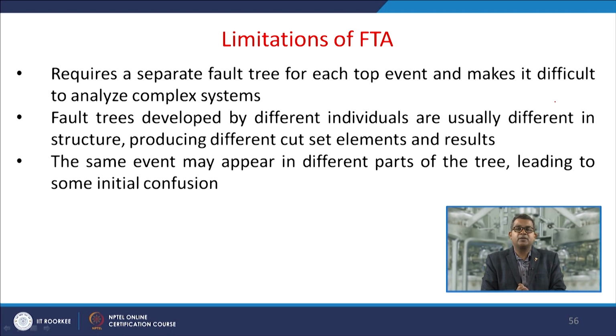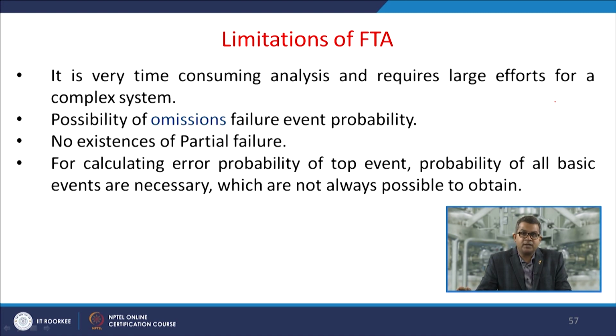Let us have a look at the limitations of fault tree analysis. They require a separate fault tree for each top event, which makes it difficult to analyze a complex system. Now, fault trees developed by different individuals are usually different because they depend on their own perception. So, they are usually different in structure, producing different cut set limits and results. So, the same event may appear in different parts of the trees, leading to some initial confusion. So, this is the disadvantage of this fault tree analysis.